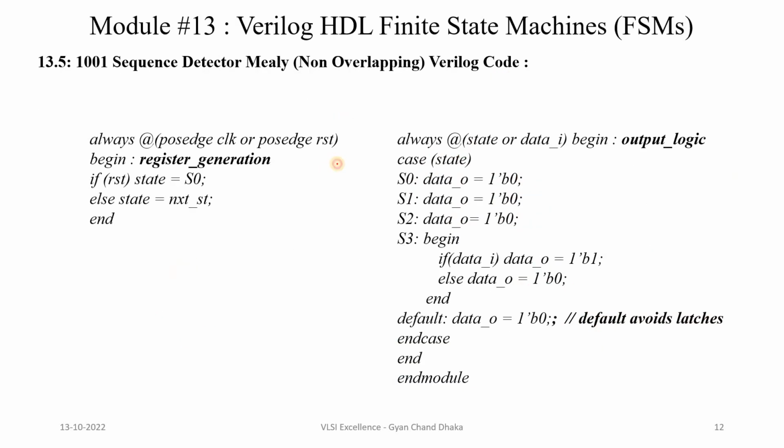So first let's see the current state logic. The current state logic is very much similar. Whenever reset, we are in the S0 state, otherwise our present state is going to be the next state.